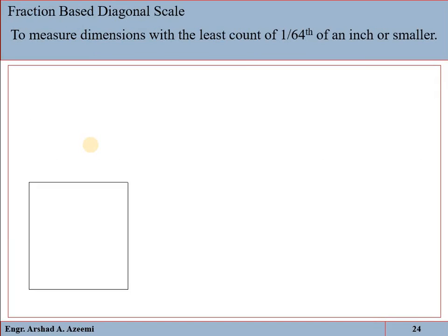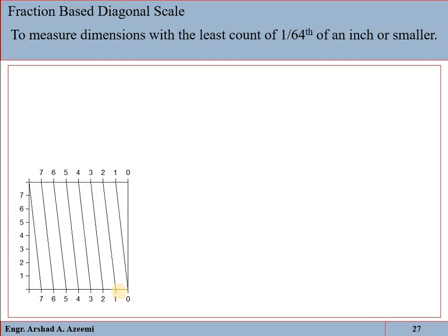Similarly, suppose you have to divide an inch into 1/64th parts. This is 1 inch distance, divide it into 8 parts, so this one portion will be 1/8. Now this one portion is further divided into 8 parts, so this one portion is 1/64th part of an inch.